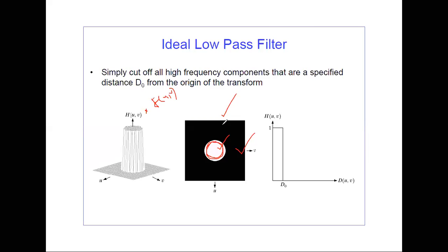All the frequency components where there is black, meaning zero, simply get multiplied by zero, and all these higher frequencies vanish, and you will be left with only the frequencies till a particular radius. Convincing enough? Do we call that a low pass filter?